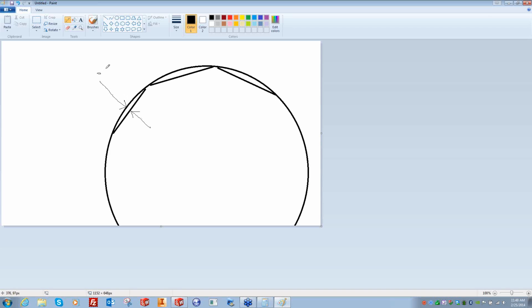So if you have 0.0005, then that's the distance here, and obviously the line gets shorter because they'd be little straight line moves in order to create a circle. They'd be a bunch of series of little straight line moves. I'm terrible at drawing freehand, so you get the idea. So this line will shorten the smaller this number is because that's the closer you are to the surface. So that's how surface tolerancing works.